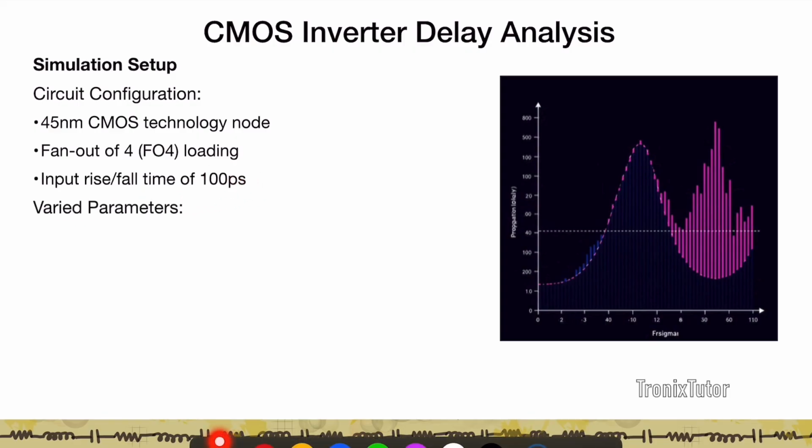So what are the parameters I'm going to vary? I'm going to vary the PMOS and NMOS threshold voltage. Here again, I'm not going to go deep into doping concentrations or channel length variation, because I want to keep the abstraction level slightly higher since I'm looking at circuits. When I'm doing device Monte Carlo, I look at the process-level abstraction.